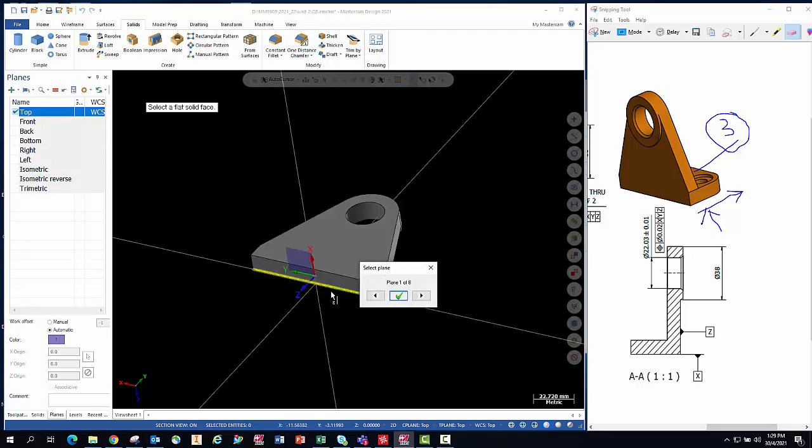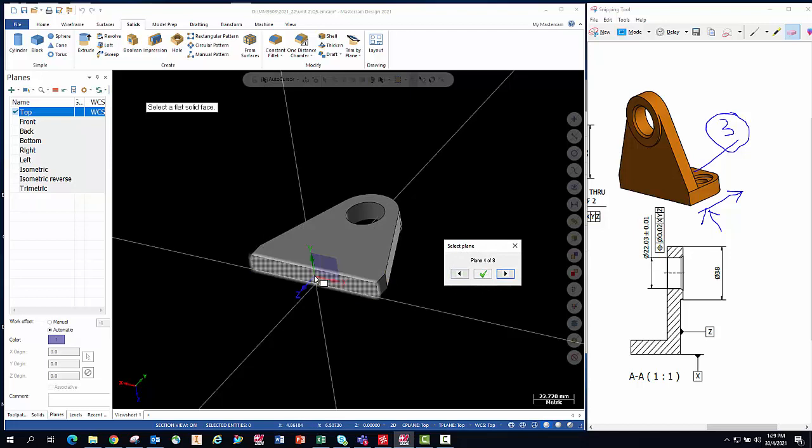Here you can see that we have the coordinate system x, y, z. We like to sketch with x pointing to the right hand side. So here we have a number of choices. You can toggle over here and say forward. Now x is still pointing this way, y is pointing down. Again forward and forward. Now this is the correct orientation with the x pointing in the right way. So we are satisfied with this orientation. We say OK.